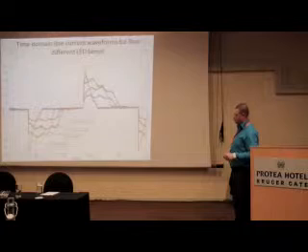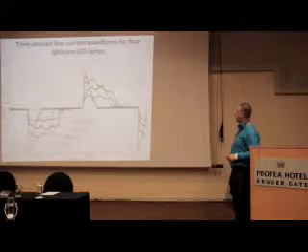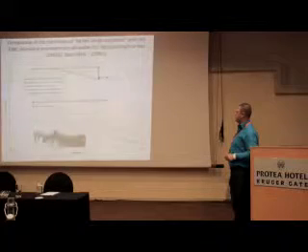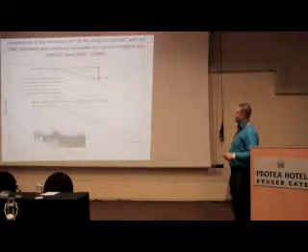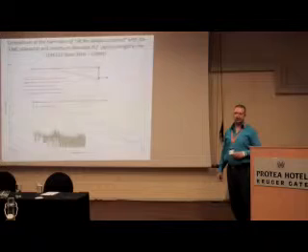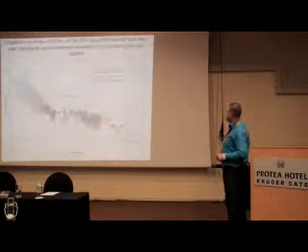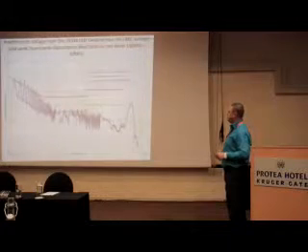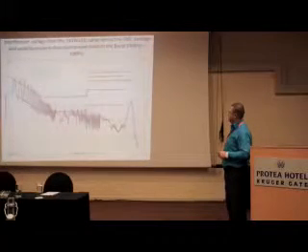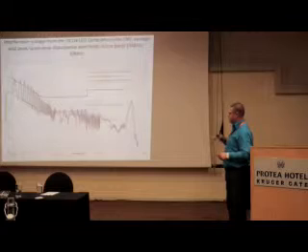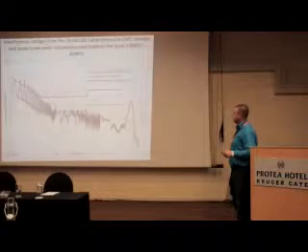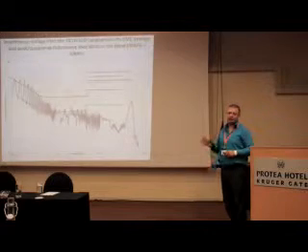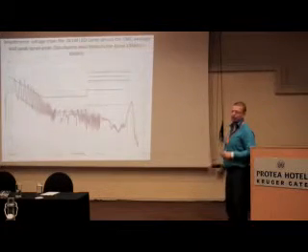It's the most affected here, the power line channel we see. From 3 kHz to 150 kHz, we see the LEDs are friendly with the EMC. But from 150 kHz to 30 MHz, they compete with the EMC signal, the maximum allowed signal, or sometimes they exceed it here. So the LEDs are good, but not the best probably, or the best, we will see.